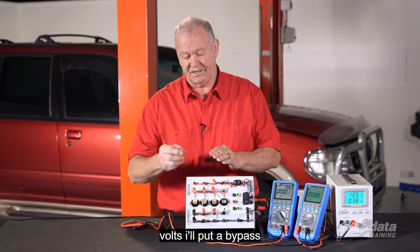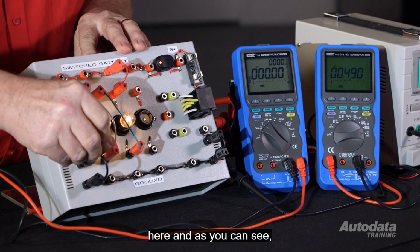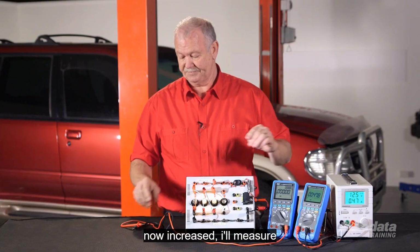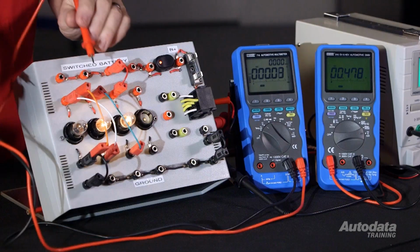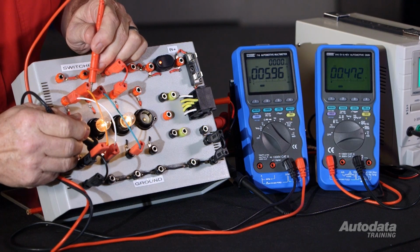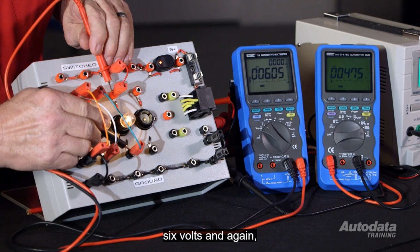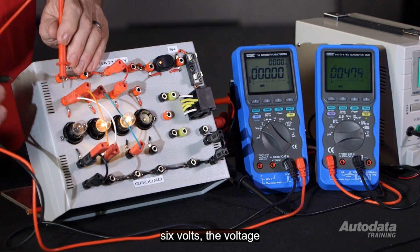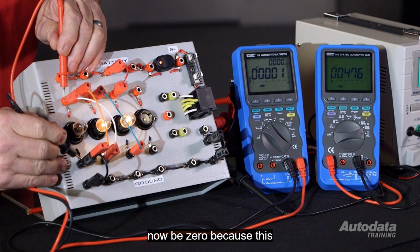I'll put a bypass in. I'll bypass this globe here. And as you can see, the current has now increased. I'll measure the voltage drops across the working globes. 6 volts, and again 6 volts. The voltage drop across this globe will now be 0.